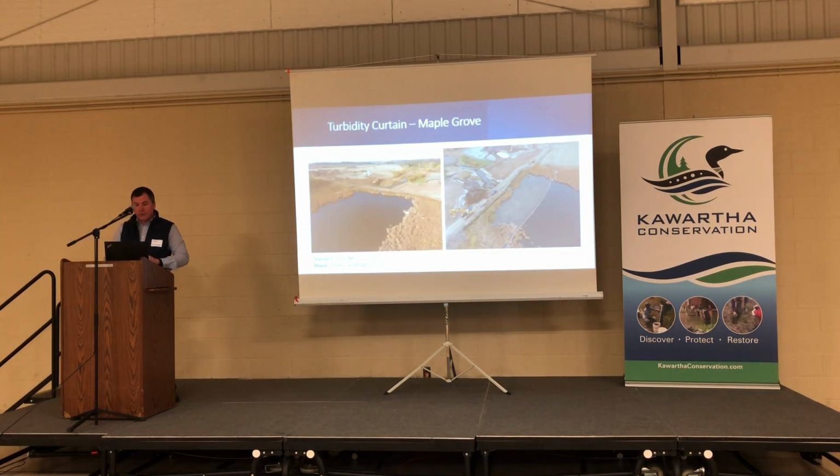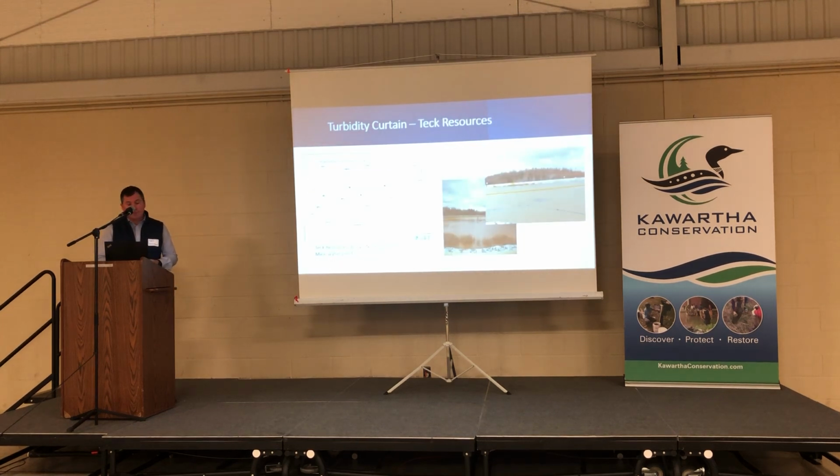These are just some different pictures, the last few slides of the presentation, looking at some of the installations. This is a project near Cambridge, Ontario. This is a land development project with potential to develop a lot of silt and sediment into this water body. So the installer deployed a series of the OPSS type specs across in one continuous link, and it does an effective job at containing silt and sediment. Not a lot of anchorage required in that installation because it's a fairly well protected water body.